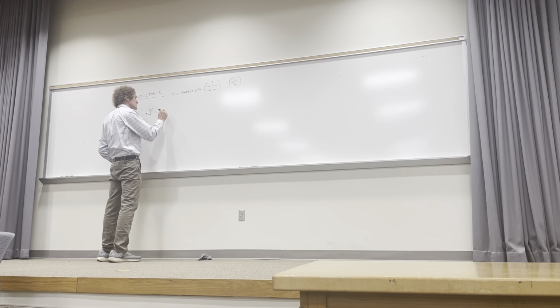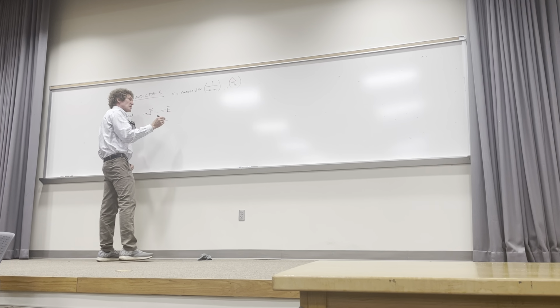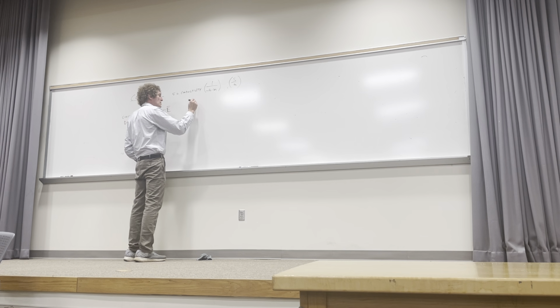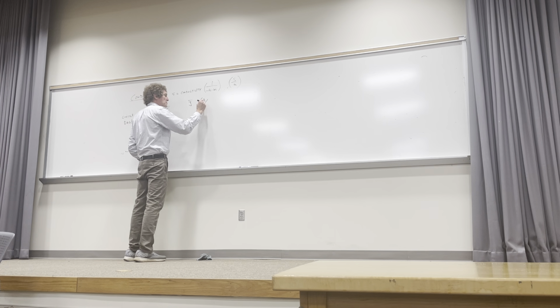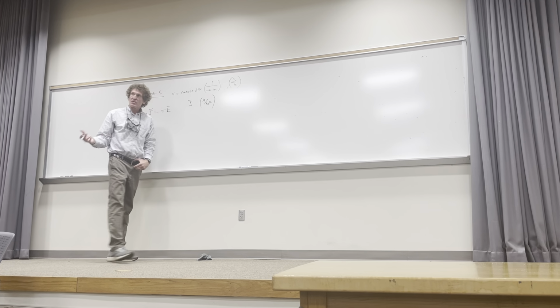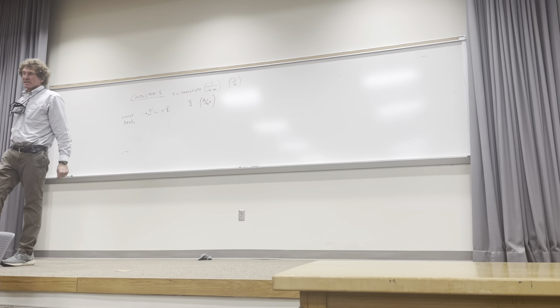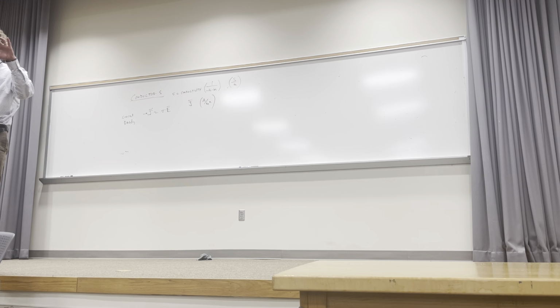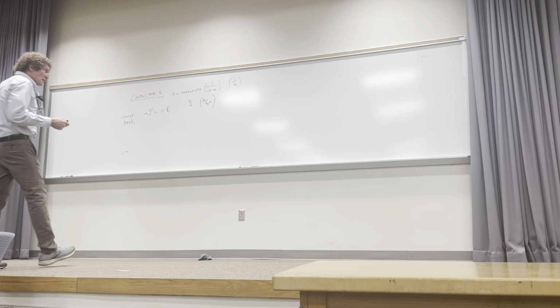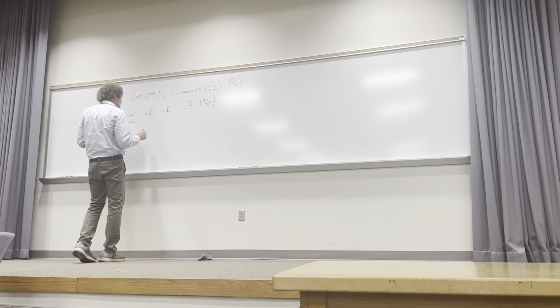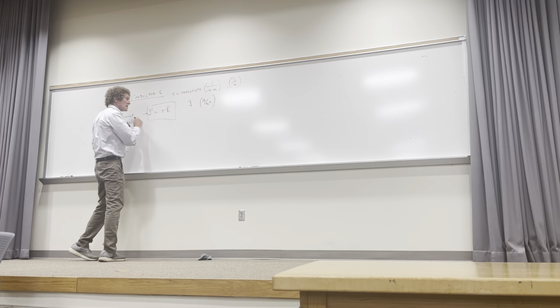E is the electric field in volts per meter, and J has the unit of current density, or amps per meter squared. Just think of current density. Current is amps. Density means how much current flows through a given meter squared of that stuff. It's really the density though. Y'all follow me on that, class? Just like charge density. So this is the current density.